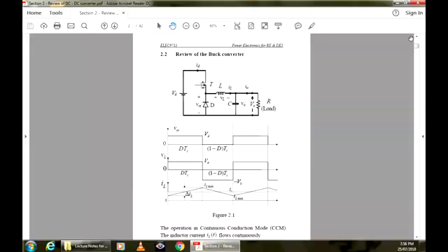Normally, the switching frequency is selected from some other considerations, like how big a capacitor we will tolerate, how big an inductor we will tolerate, and how much loss we will tolerate in these devices. So from those points of view, the switching frequency is normally determined. But then the switching frequency is also subject to what device we choose. If it's low power, we can use MOSFETs, and the switching frequency can be from 10 kilohertz to several hundred kilohertz. But if it is an IGBT, we don't have much option but to keep the switching frequency around 15 kilohertz, 20 kilohertz. That's all.